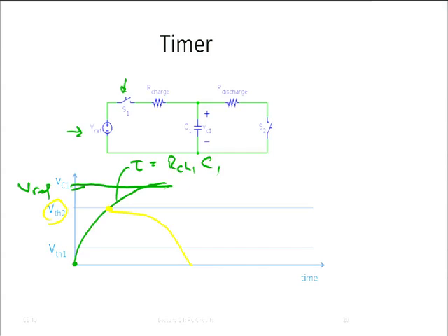As we get close to 0, the voltage across VC1 is close to 0. Well, it's small, right? Consequently, the current is going to be small that flows through our discharge, and hence the rate of discharge is going to be very small also. So it has to be the other way around. I want you to be able to think about it in this qualitative way, because if you're like me, a little bit mathematically challenged, this is a much more circuit way to understand it.